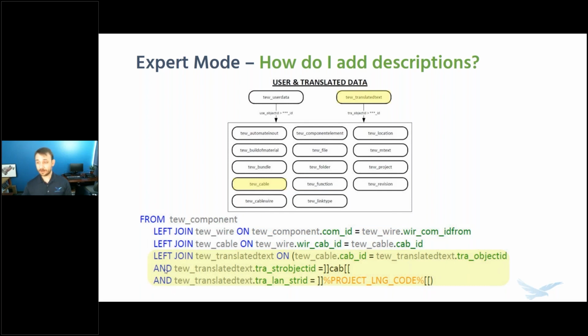We're going to add an AND factor, so we're actually joining on 3 different things on this one. The stored object ID equals a cable. It's just to help filter it out and prevent it from grabbing any wrong information. The likelihood that you have 2 IDs that are the same is very unlikely, because the application applies unique IDs to everything. This is just a little extra redundancy to help prevent cross errors if possible.